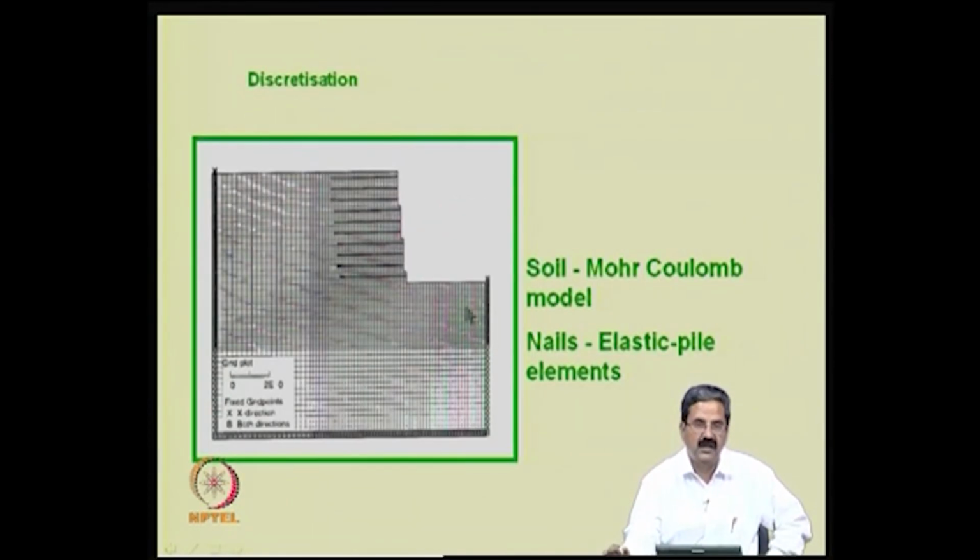So, actually you can design this the way that I told you, how to calculate earth pressure, K naught into gamma h, and that is the earth pressure acting, right. So, what is the pressure that you have to resist, how do you get it? You have to calculate the friction between the soil and reinforcement.